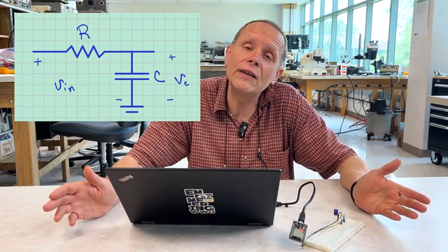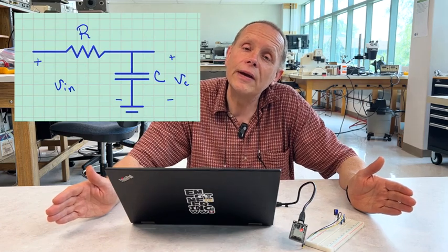And in our case here, we have an RC circuit. Notice the picture on the screen. You see the resistor and the capacitor. So when you hook this circuit up to an input voltage, Vin, say it jumps from 0 to 1, then the current in the resistor starts flowing because you can't change the voltage on the capacitor instantly, unless you have an infinite voltage or infinite current source. So essentially, what happens is that the capacitor slowly charges up. And it gets slower and slower and slower the closer it gets to being fully charged.